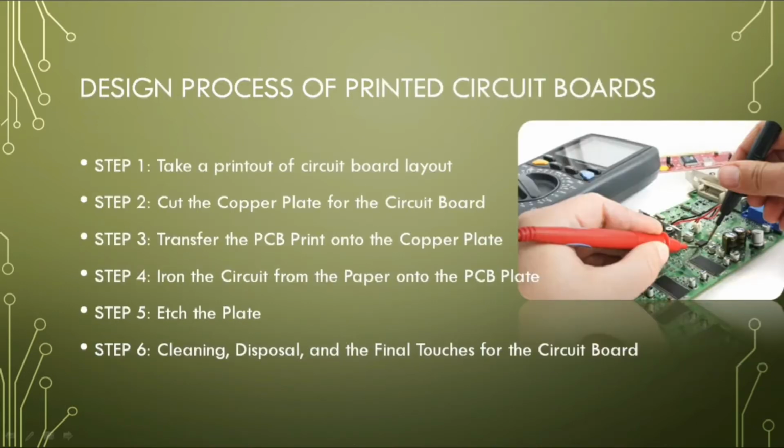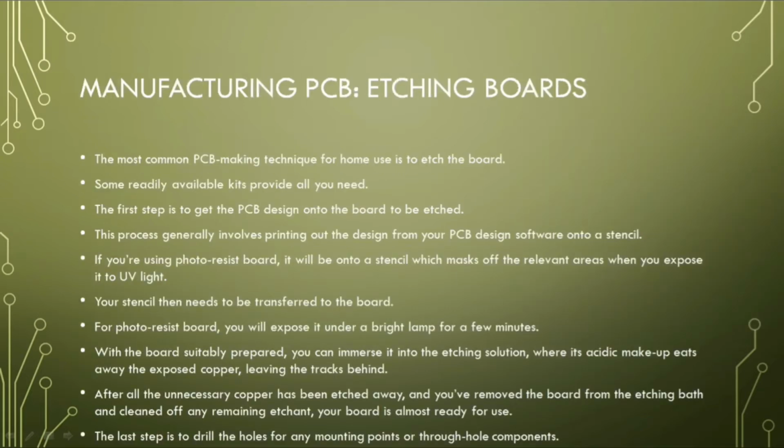Professionally manufactured PCBs undergo different processes to make them simpler to use. It starts with designing the schematic view of your PCB. This step lets you lay out the components logically and make the necessary connections without having to worry about exactly where they will sit in physical space. One can use different software packages to design these schematics. When you are happy with the schematic design of your board, you can proceed to laying out the physical board. There are no hard and fast rules on how to arrange the board, but it makes sense to keep together groups of components that constitute an area of functionality. For example, components related to power supply can be kept together for a more logical layout.